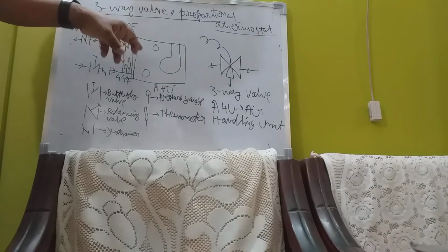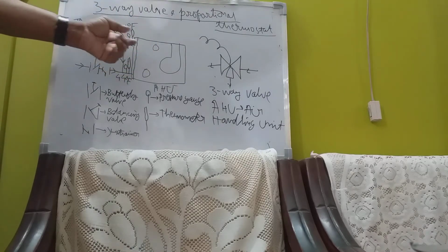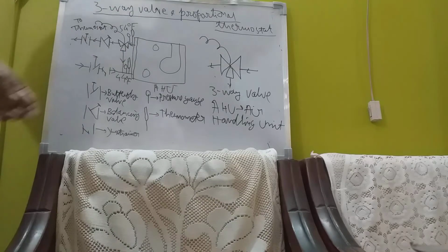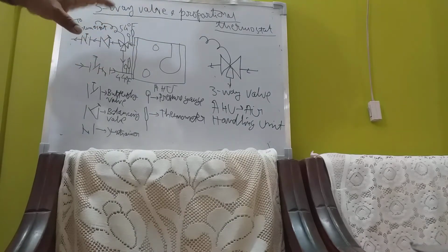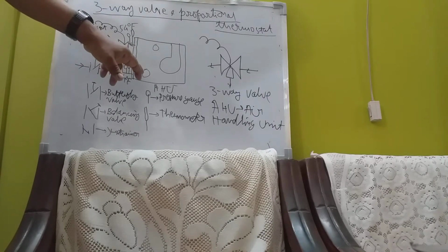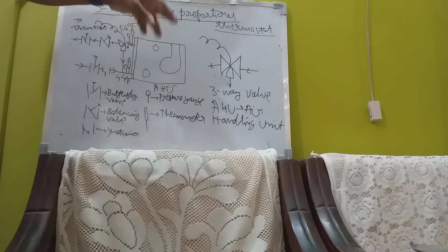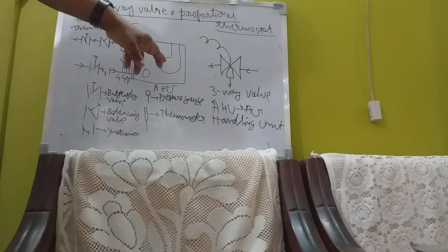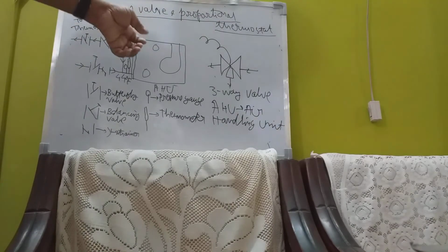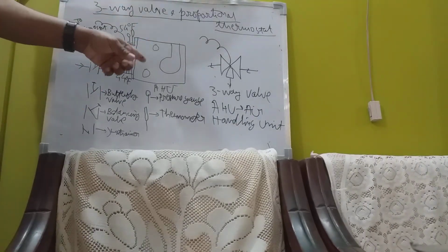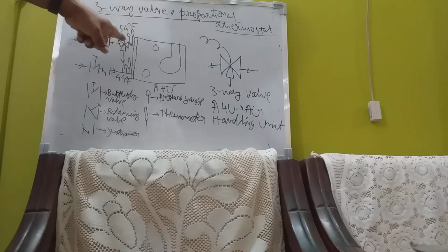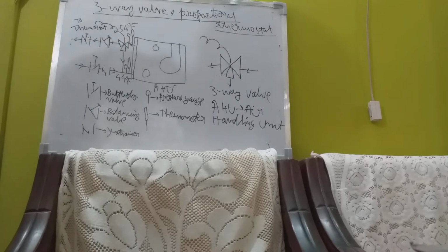cooling coil. Since chilled water comes here and air is passed through, the blower sucks air from this pre-filter. Now, as it passes through the chilled water pipe, it gets cooled. The chilled water comes at 44 degrees Fahrenheit, and it transmits the coolness to the air. Giving coolness to the air means what? It picks up heat. The chilled water picks up heat. So from 44 degrees Fahrenheit it gets heated to 54 degrees Fahrenheit, and at 54 degrees Fahrenheit it goes out to the chilling system.